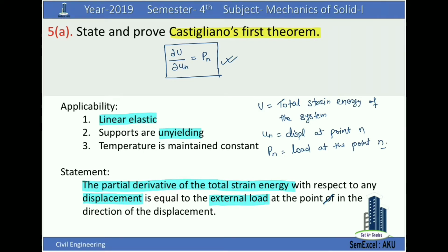We will see what does this linear elastic mean. We all know the Hooke's law. Stress is equal to Young's modulus of elasticity into strain. If you plot this relation, stress versus strain, if the curve is a straight line, then this material is known as the linear elastic material, right? But let's say the curve is like this, then this is not linear elastic, this is non-linear. So hope you get idea what is linear elastic material.